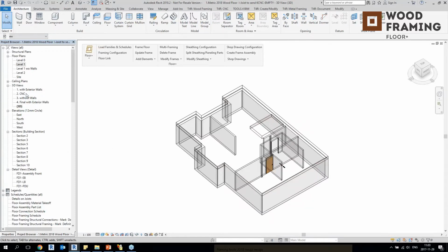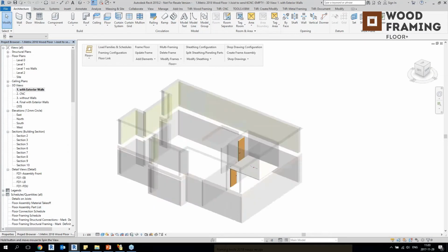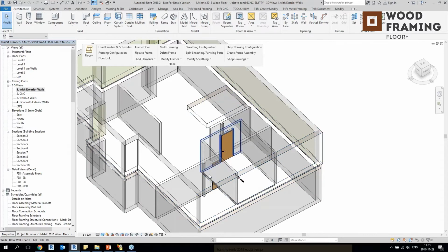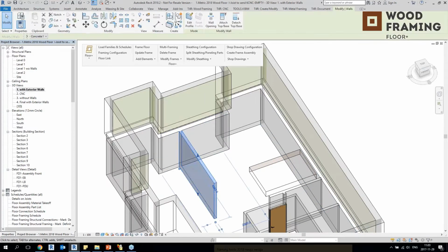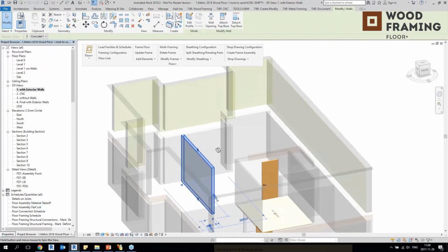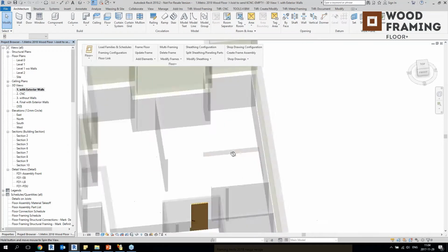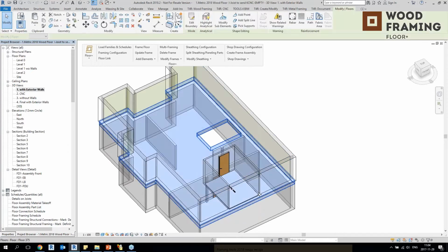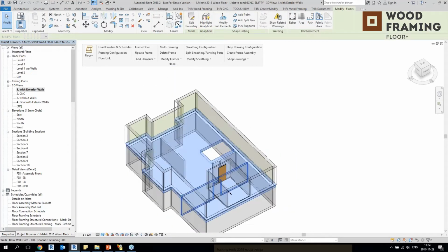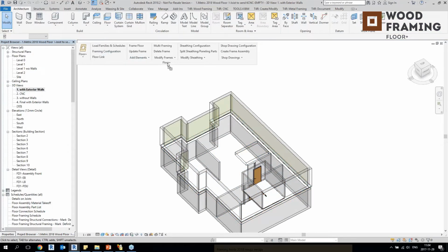You can see it in this 3D model that I have, this basement floor. I also have this bathroom where my floor will be less thick. I will also add the joists right here where they will overlap each other above this wall in the basement. And we can also see a simple opening right here that we will frame and then modify. So, of course, we have to make our model in Revit correct before using the framing tools. And when we do that, we can configure everything for our framing.